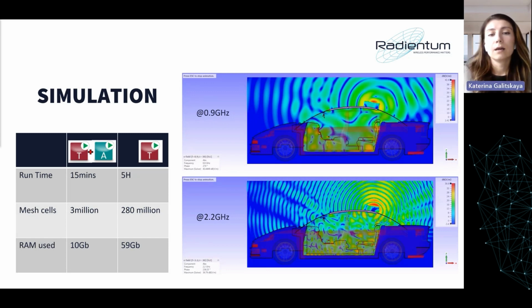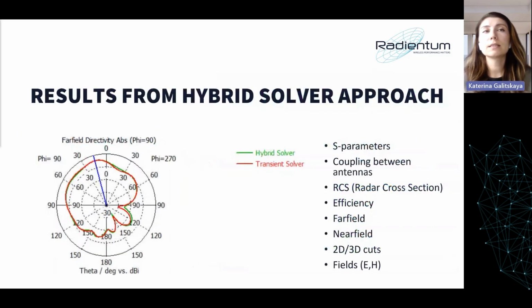On the next slide, we can see a comparison of radiation pattern cuts at 2.6 gigahertz, on the high frequency of that antenna, and this is a comparison of two methods: one model, one solver, and assembly plus hybrid solver. The thing with the asymptotic solver is that you can choose the accuracy level, and in this case I chose the low accuracy level just to run a quick approximation. Usually the biggest difference is noticeable at back radiation and in null levels, but it can be tackled by increasing the accuracy of the asymptotic or integral equation solver.